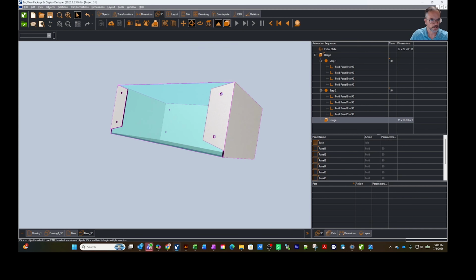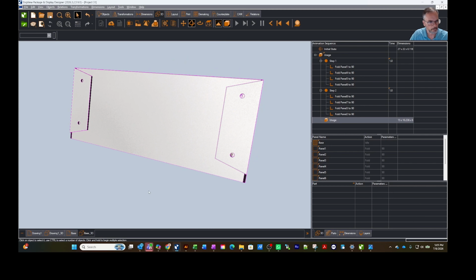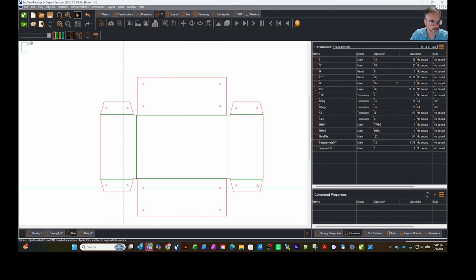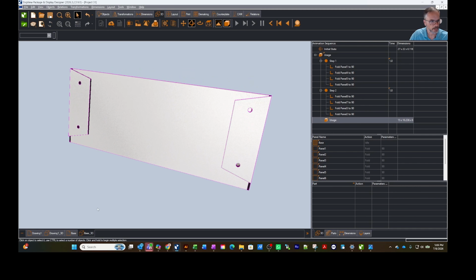So we're going to refresh. And if you look there, the hole is just slightly off. I think it's off by material thickness because that's the fold that's taken into account. So let's come to this HHO2 and let's minus our material thickness. And let's take a second look at it or refresh and look at there. Our holes are lined up just nice and perfect.